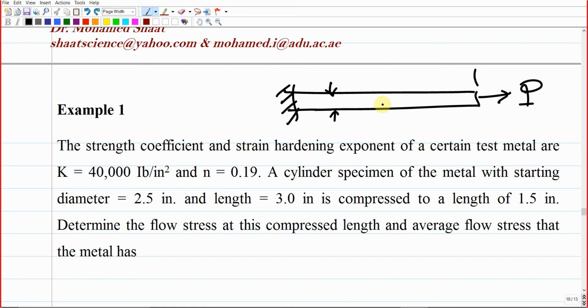Because when we define the true stress for a tensile test bar under tension, it should be defined at the length that we originally want to change in this material. What is the objective of this metal forming process? The objective is to change the length from L0 to Li, the instantaneous new length. So that's why the true strain should be based on Li over L0.